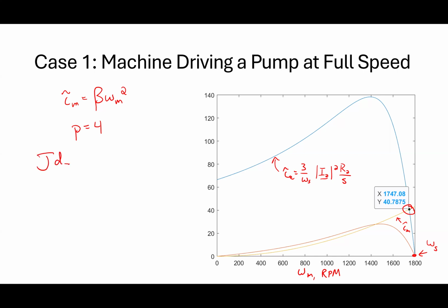It's a good question, right? Newton's law always applies. Torque electrical minus torque mechanical. Steady state in general basically means where does everything become constant? So in other words, where does the speed become steady? So where the speed is constant, what's true about d omega by dt? It equals 0. Torque electrical and torque mechanical are equal there.